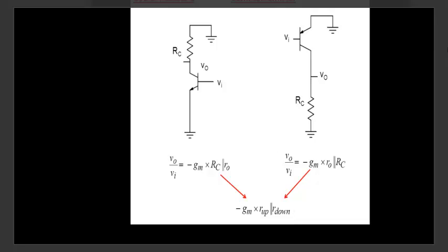And we've been telling that, whenever you have to build a gain at any particular point, or you want to know the voltage at any particular point, what you do is you build a Norton's equivalent at that point. So when we build a Norton's equivalent at this particular point here, you'll get a Norton's current. And how do you find the Norton's current? Well, you take this node and ground it, and then this one is nothing but Gm times Vi. So that's the Norton's current.